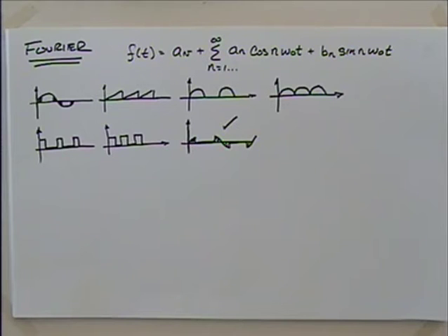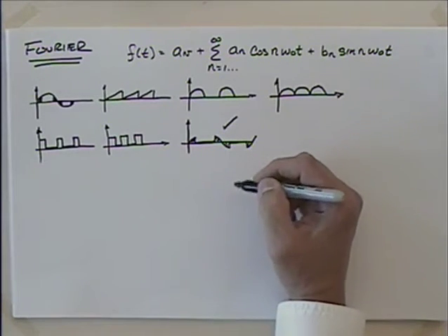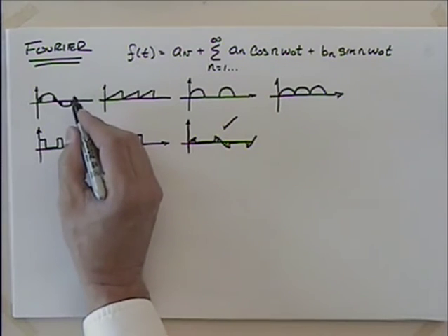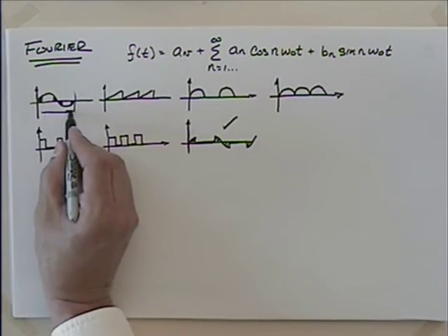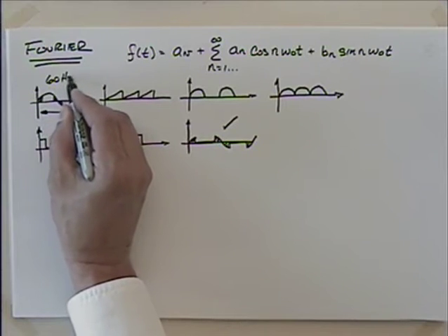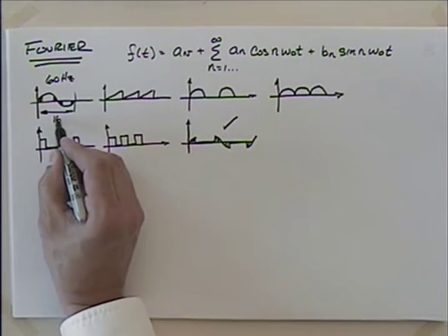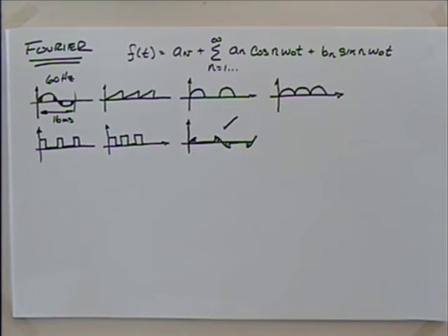We don't have to then have as robust of mechanical components that the thing drives. The reason that we haven't been doing this for too long is, well, we've been doing it with some DC drives and things like that, but using AC, it wasn't until recently that we had a computer that could compute fast enough. I mean, if we look at a 60 hertz signal, how much time do you have in here? About 16 milliseconds? Okay, so you've got to do some pretty significant calculations in 16 milliseconds to pull this off. So that's not a problem now with computers, but many years ago, it was. So those are some periodic signals that we can definitely use this on.